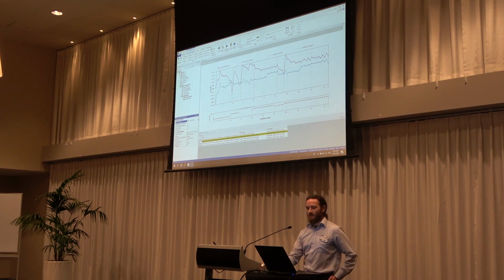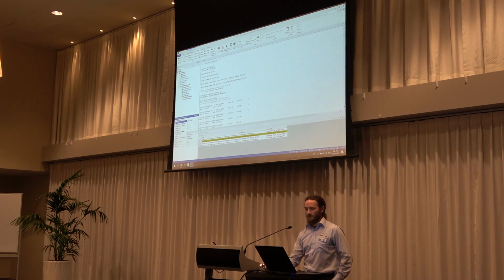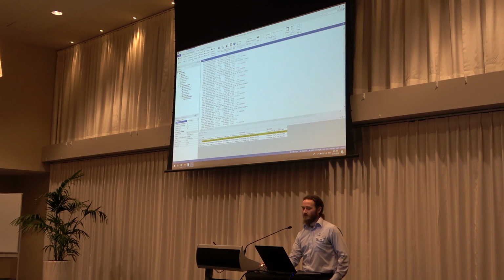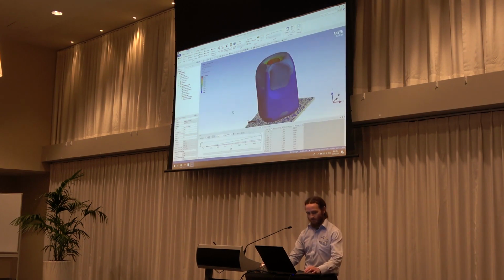But if we go to the solver output and scroll down, that's going to take too long. Here we go. So there's our usual implicit convergence. And you can see here it says transitioning to explicit method. And now it's time stepping using an explicit method instead of an implicit method. And then that marches on and solves. So if you want to have a look at that, let's generate an animation, 20 frames.